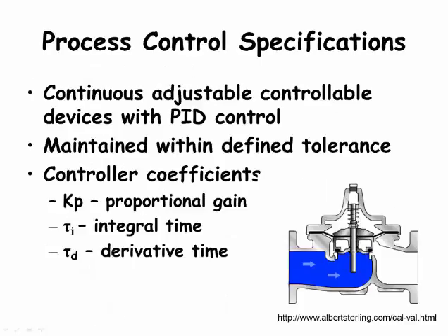To be able to use PID control, the actuator needs to be continuously adjustable. For example, the adjustable diaphragm flow valve shown in the slide could be continuously adjustable. However, the 2-position solenoid valve you used in the actuator lab cannot be used as a flow controller. Relays turn motors on and off. You would need a variable frequency drive actuator to drive the continuously adjustable motor speed you might want.